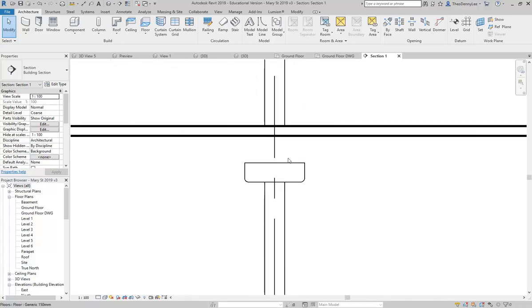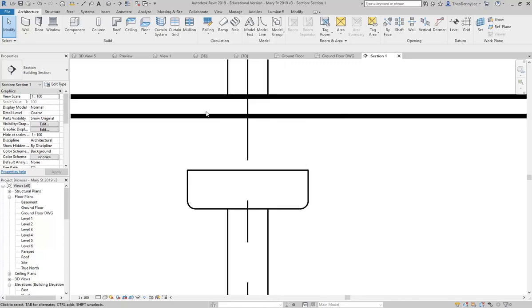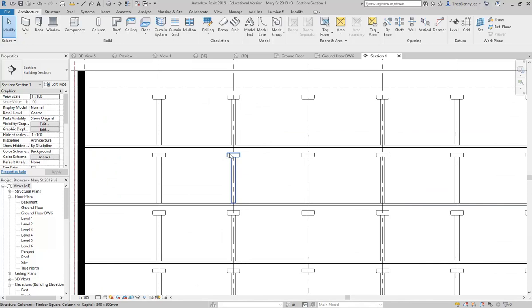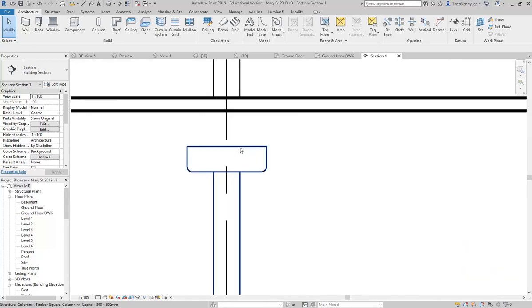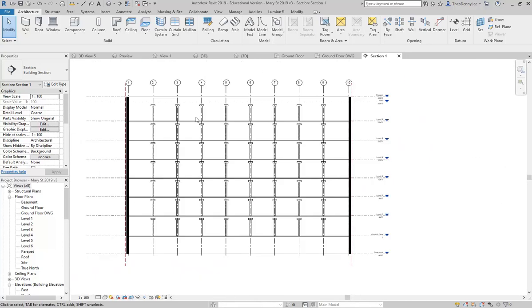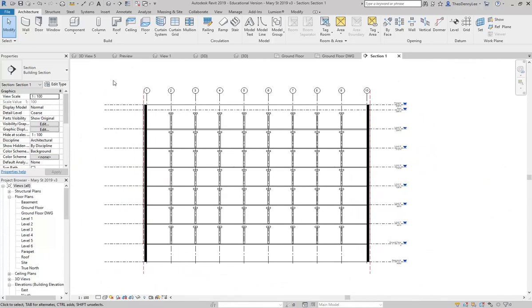Yeah, that's right, the ceiling, if you're going to have a ceiling, it would sit at the top of the column. But I'm not going to make a separate ceiling, so I'm going to have the floor joists and then the beams sitting under the floor, all exposed. So that's why I'm leaving the gap. But that's how it is in real life. If you were to put a ceiling in, the ceiling would come down here. And that's definitely an option. We'll talk to you about fire rating to separate the floors maybe later. But that's not a bad option to have a lined ceiling.